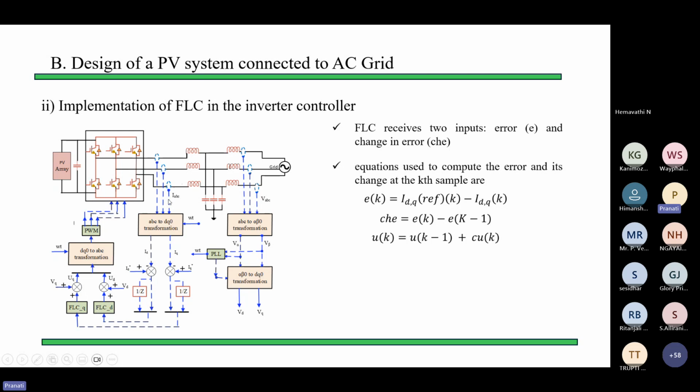Now I_A, I_B, I_C are the currents in the ABC coordinate. To simplify, we have to work with the direct and quadrature axes, which are DC values. It is easier when we convert this ABC coordinate to DQ0 transformation.